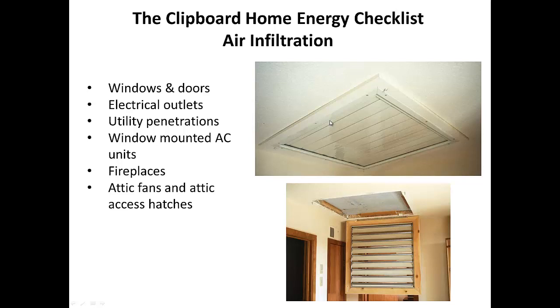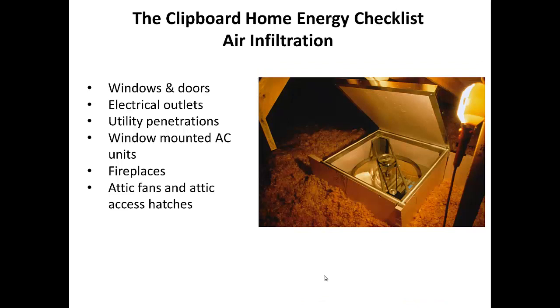This was on a piano hinge, and I would drop it down into the down position, and then once a year I would put this cork up there, use weather stripping to make it airtight, and then I'd take it down in the summertime so I could use my attic fan and cool my house down at night, and then close my house up during the day. And it extended the period of time when I did not have to use air conditioning.